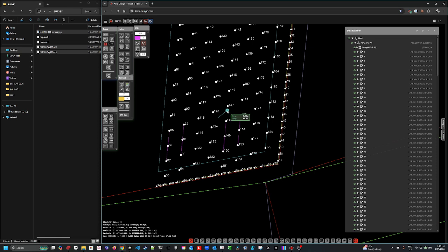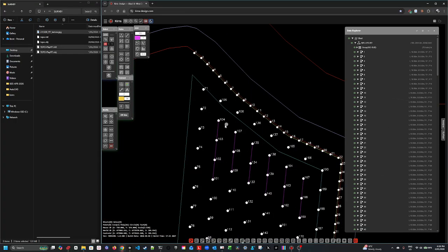So now I've got that there. I don't want it, so I'm going to right click and it's going to ask me, oh, hey, a line needs 2 points. I'm going to discard that. Click here. Not that this needs moving, but we'll just do that. So we've drawn our line. Another right click to get out of that tool, and we're going to extend these lines to these points. Pretty groovy. I love this tool. It's one of my favorite tools in any application. Line extension, I just think it's a very cool tool. Wrong one.